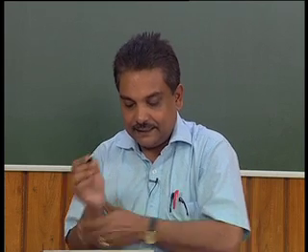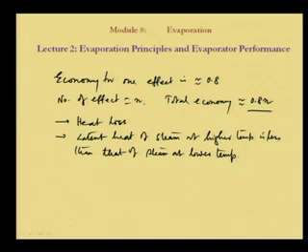And also another point, that there will be a heat loss during this process. Okay. So, therefore, the amount of vapor generated will always be less than the amount of steam that is being used for that. So, therefore, the economy is always less than 1.